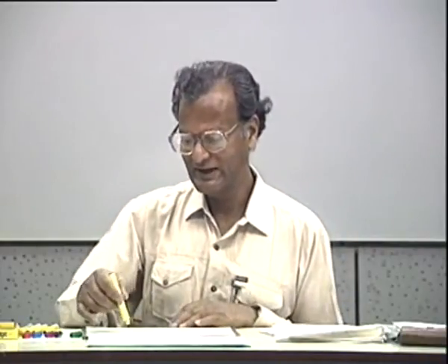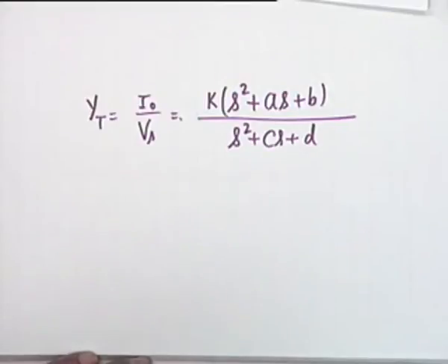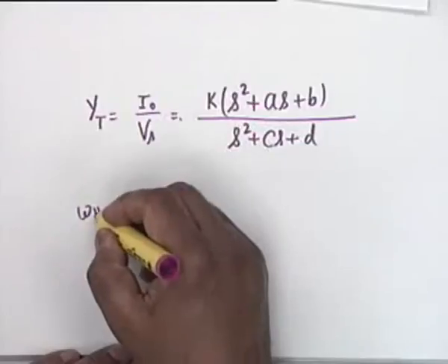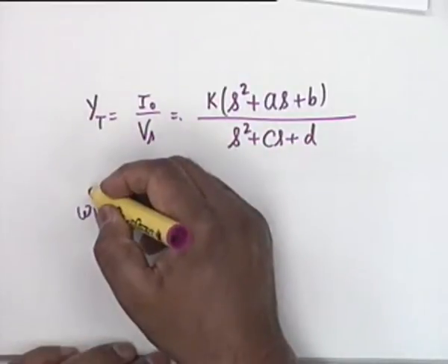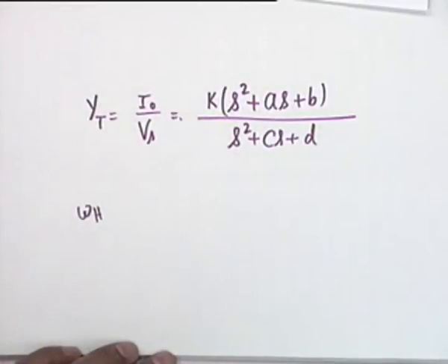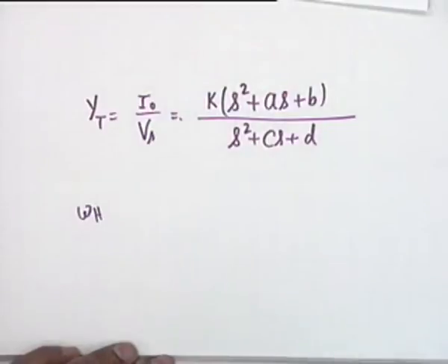We don't want to find K, A, B, C and D and solve the equation exactly. If you solve it exactly, what would be the order of the equation to be solved for omega H? It would still be quadratic in omega H squared. So, it's not too bad. Although it looks complicated, it's not too bad. Only thing is your A, B, K, C and D have to be found out. So, we will go the shortcut way. We will see what the method of open circuit time constants gives us.